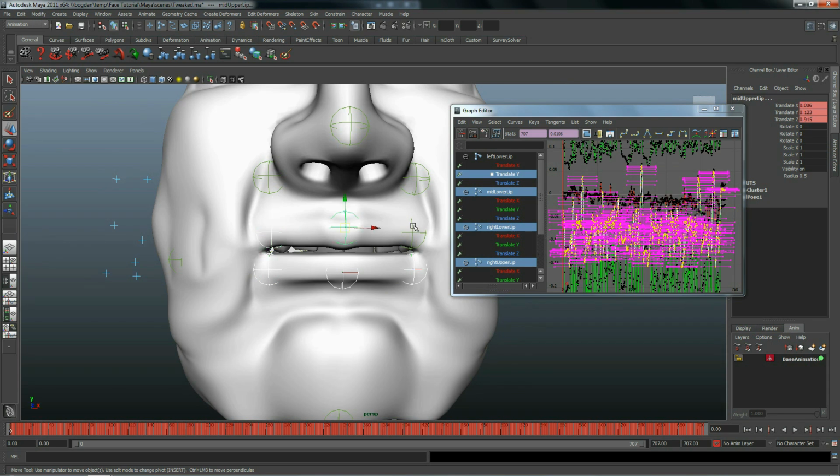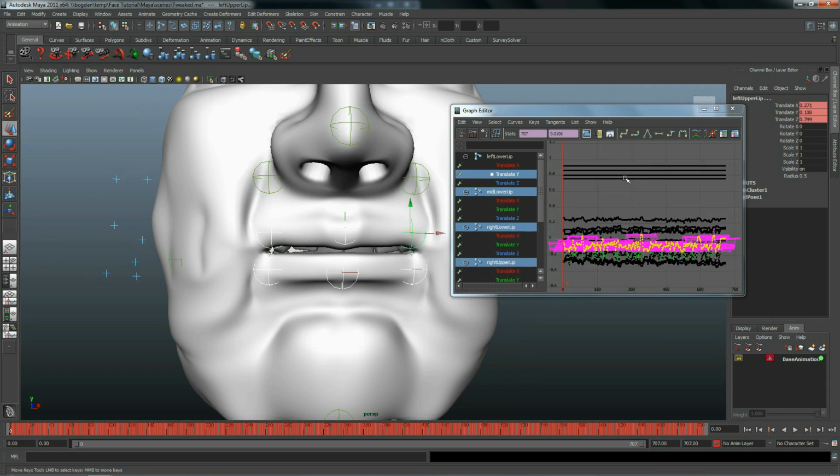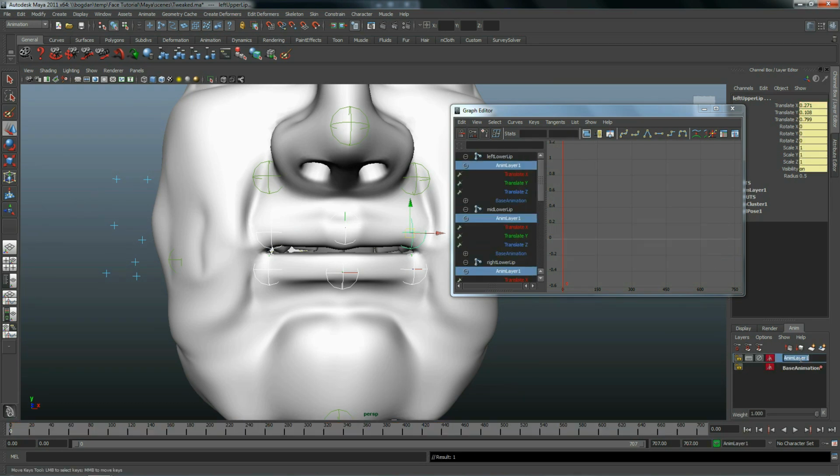Begin by selecting all the bones that you intend to edit. Select the Animation Layer tab and choose Create a Layer from Selected. Give the layer a name for easier management. Now, click on Set Weight to 1 and Key Layer. This will activate the layer and allow us to view any changes that we make.